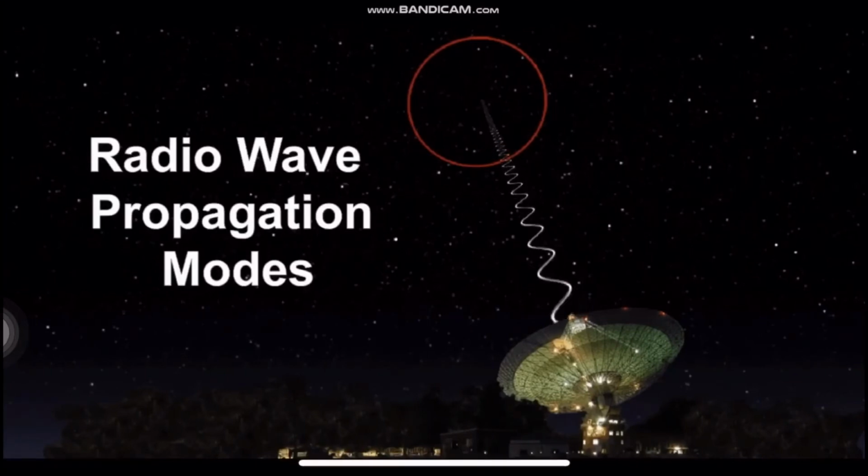Radio propagation is the way radio waves travel or propagate when they are transmitted from one point to another and affected by the medium in which they travel, and in particular the way they propagate around the Earth in various parts of the atmosphere. It can propagate from transmitter to receiver in four ways: through ground waves, sky waves, free space waves, and other field waves. Ground waves exist only for vertical polarization produced by vertical antennas when the transmitting and receiving antennas are close to the surface of the Earth.